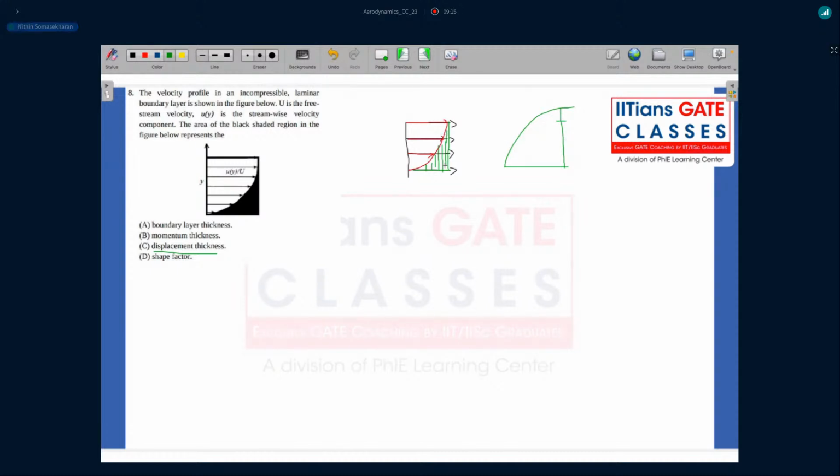So this deficit of mass flow rate basically tells us what your displacement thickness is. And if you look at the other option, boundary layer thickness, it's a very general term. The boundary layer thickness is basically the height from the bottom towards the end of the boundary layer. So this shaded region does not really exactly represent that.